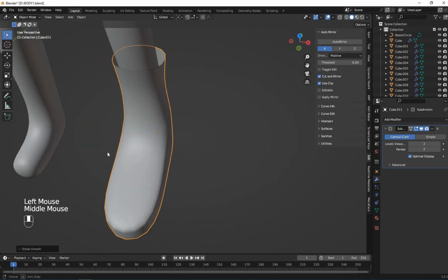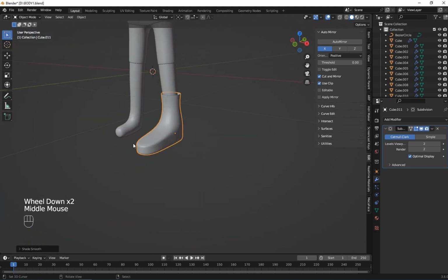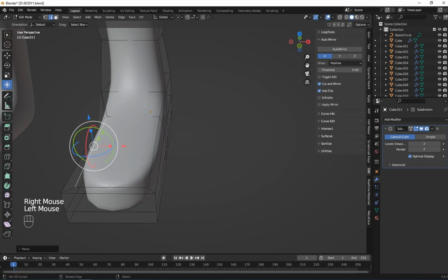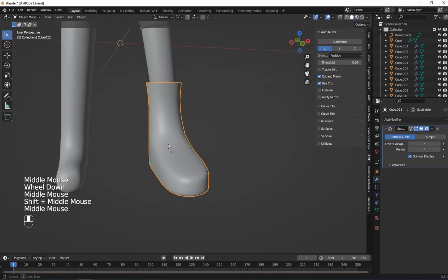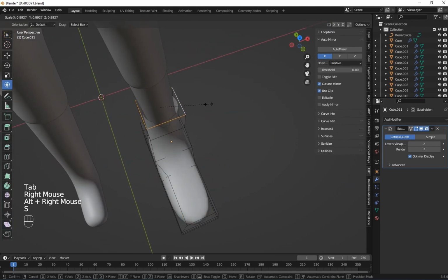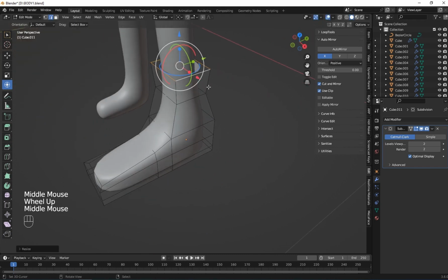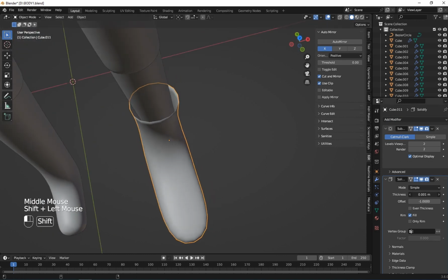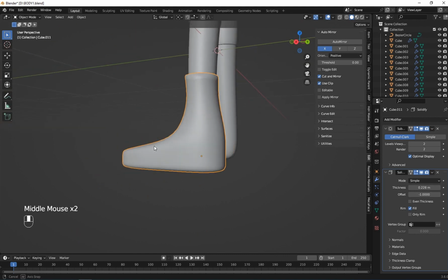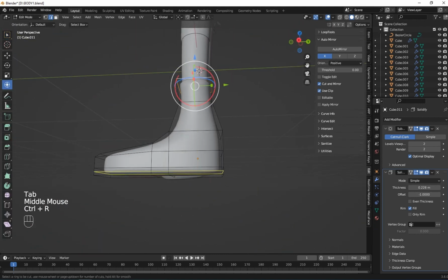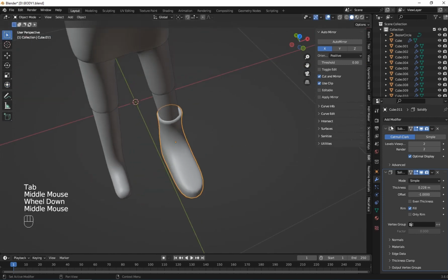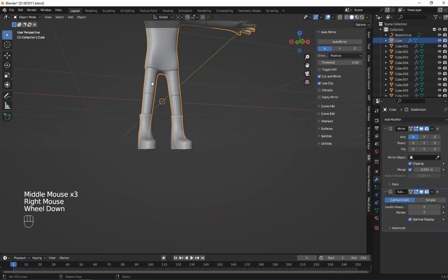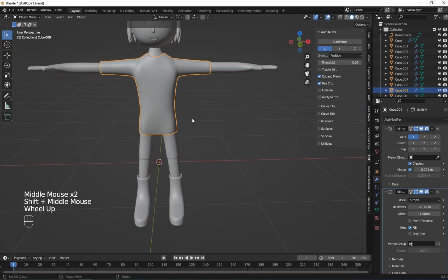Let's set shade to smooth, and we got something like this. Let's design it. Let's see. So let's add a solidify modifier to it, to give it depth. Nice. Now let's give it a mirror modifier, and let's use the character as our source object. Nice. So congratulations.